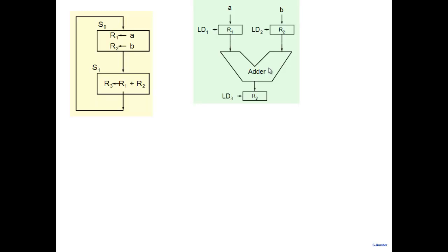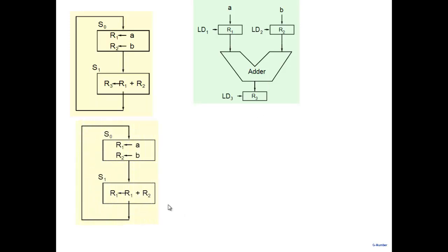Right? Similarly, I can think of my registers. Registers are being used for a certain part of my computation, and that same register is idle, not being used, for another part of my computation. So in general, when I'm constructing this RTL design here, I should look at, besides minimizing the number of states and all that, am I using my registers and adders more efficiently? So for example, can I do this?